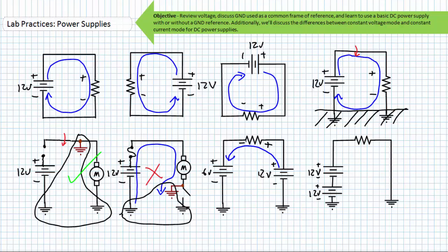Finally, consider our last example problem in the lower right-hand corner, where these devices seem to be aiding one another, and in fact they are. One device's negative terminal is hooked to ground, and from ground, we go up 12 volts. Now this device's negative terminal is hooked to 12 volts, and it's going up an additional 12 volts for a rise of 24 volts referenced from ground.